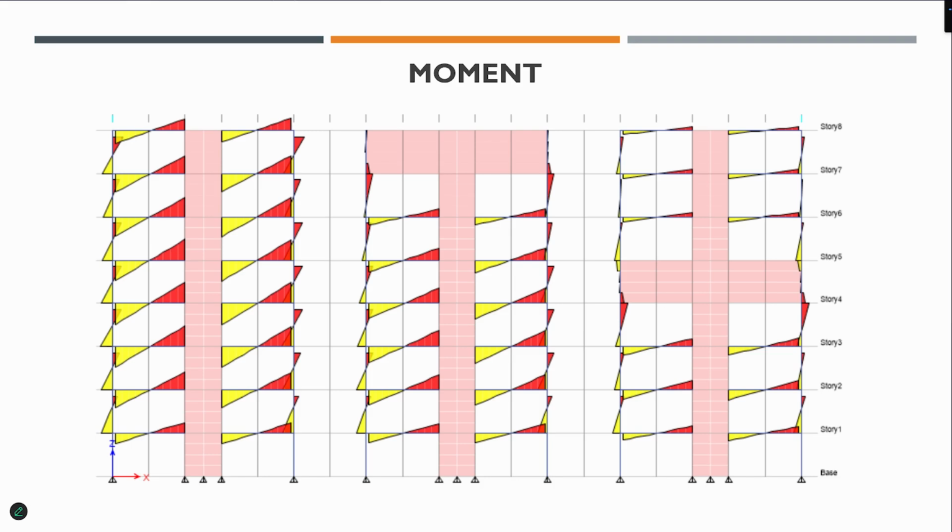Okay. See this carefully. This is one beam. Let's say it is 600 millimeter and another beam 600 millimeter. So if this has an I equal to whatever, this is also I equal to I1, correct? BD cubed over 12, right? You add them together, it will be I1 into 2.